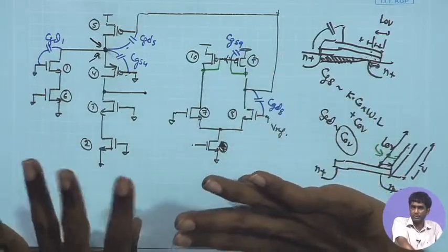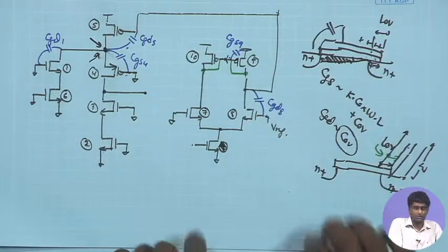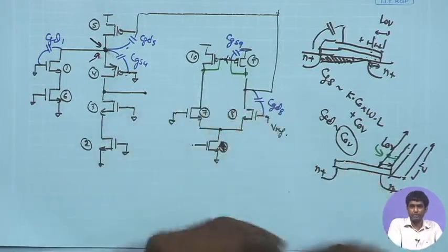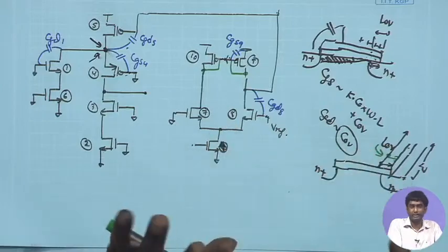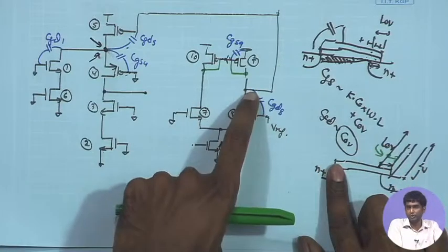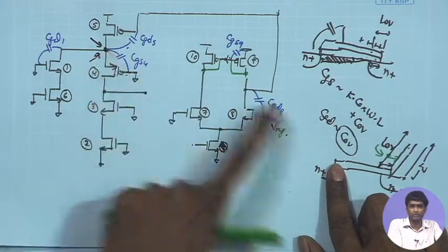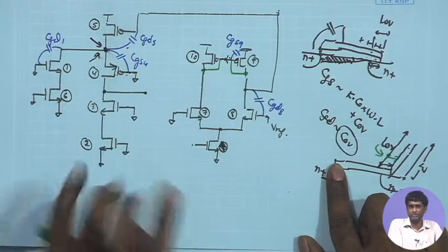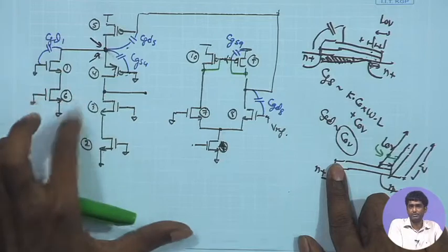and it will create problems with the phase margin. So, although for overall analysis we ignore this pole, for our particular application, if we are looking at low bias current, we have to be careful that this does not become the non-dominant pole, otherwise it will fight with this one, or it can become lower than this one, and then interfere with the compensation we are trying to achieve with the help of a compensation capacitor over here.